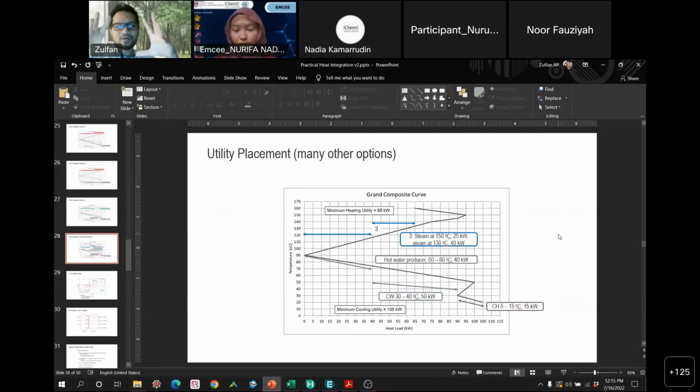So if one stream is at a lower temperature and one is at a higher temperature, we have the cold and hot stream, and if they differ too much, we will have what they call thermal stress. This one is mechanical engineering, people can tell you more about that. But we have a very high temperature on one side and a very low temperature on the other side, so we have thermal stress. This thermal stress may not be good for the material's lifetime.